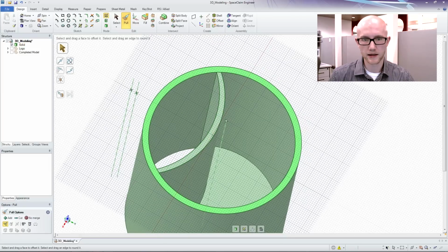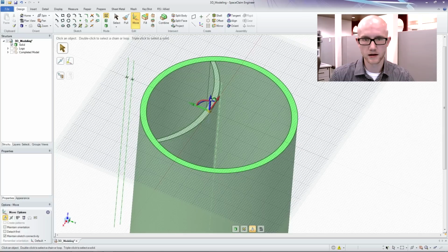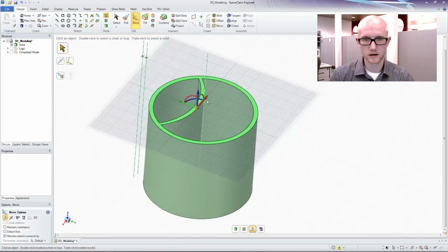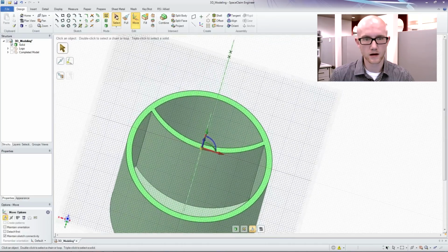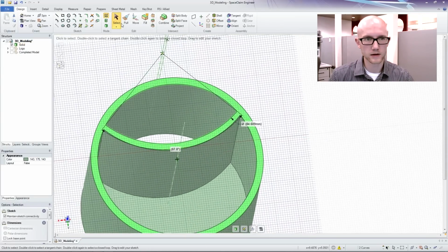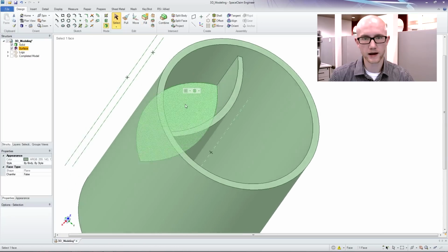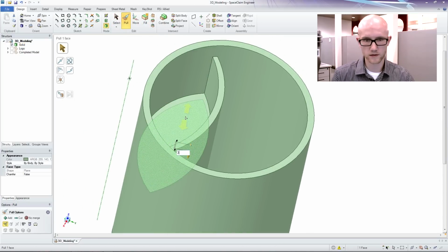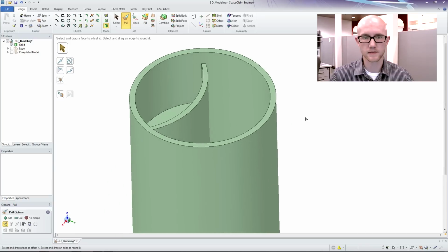And then we're going to add the base of this little outcropping. Let's move my sketch plane down a little more, somewhere in there. All right, now if I select these, I can use this fill tool to create a base, and then I can pull that down, let's say 3 millimeters, just like the rest of it.